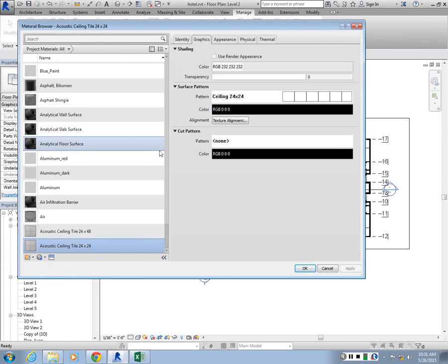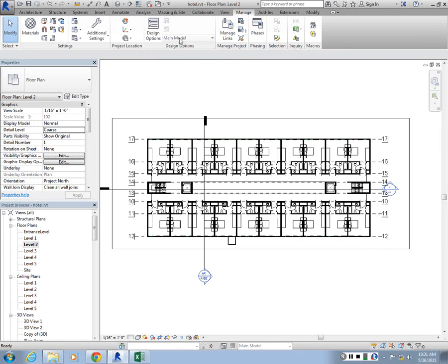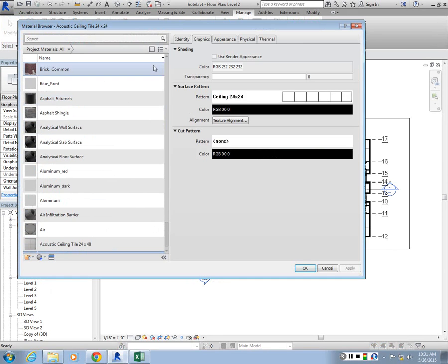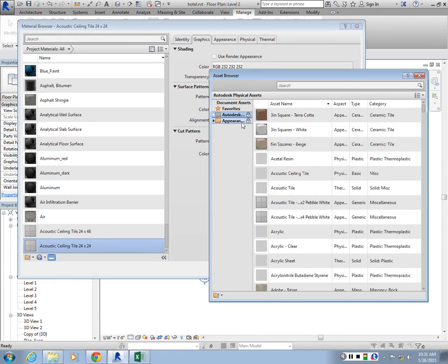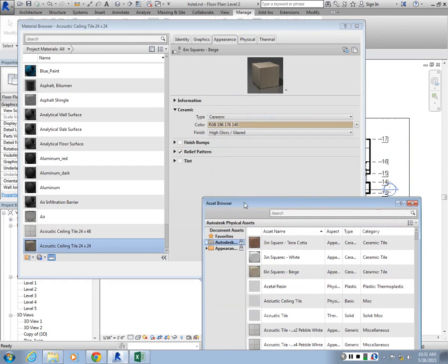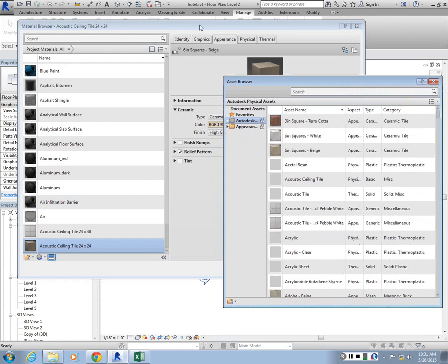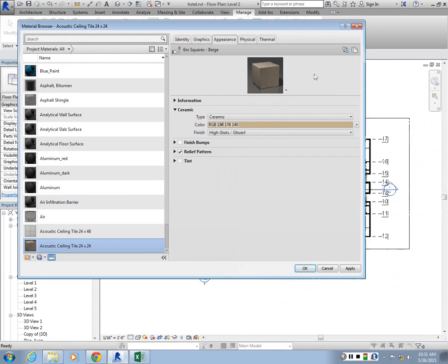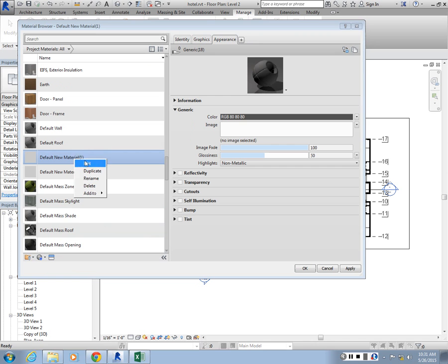So one thing to know in the Material Editor tab in Revit is that Revit has a built-in library called Assets, where there are tons of materials available, and they all have their own properties, categories, as well as different types of settings. For each material in Revit, let's say we go here, you click here and do create new material. Let's rename this, say my custom material 1.